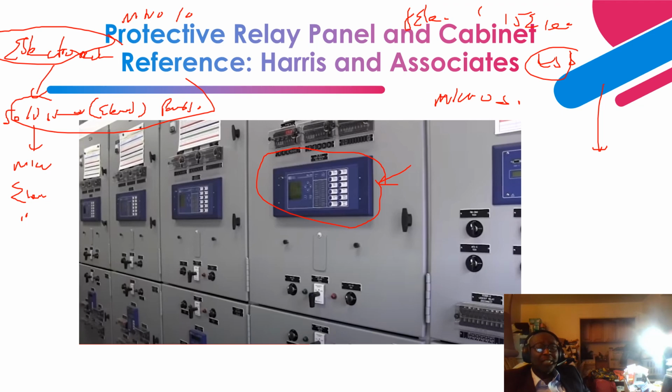So this relay lineup shows you, on the sub transmission side, all the protective relays that protect all the feeders that go on that sub transmission section of the substation. On this side are test switches, right? We have test switches that separate the CTs from the protective relay.